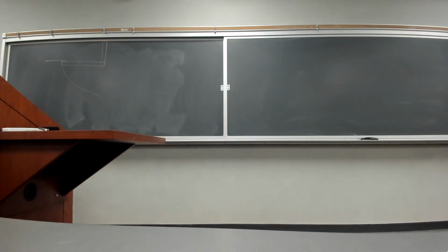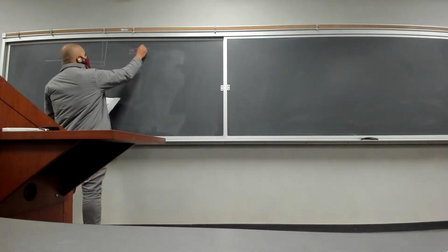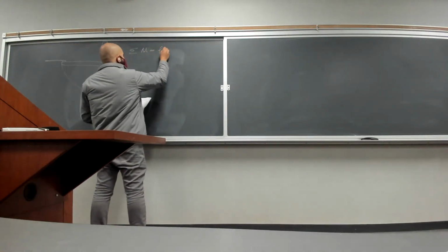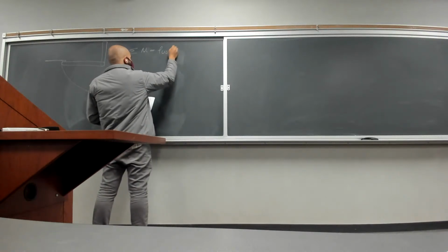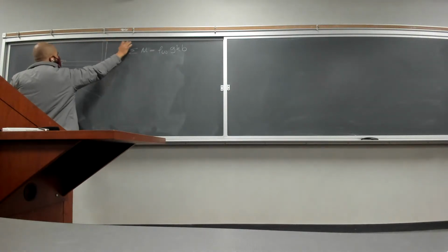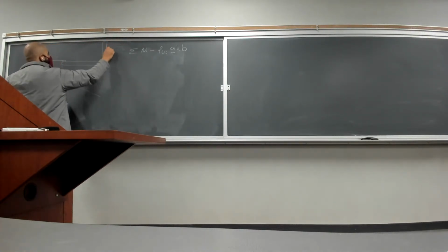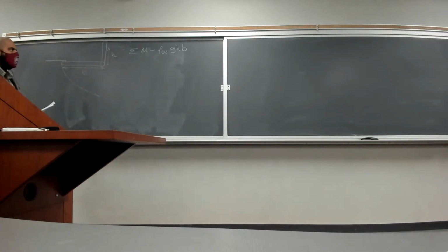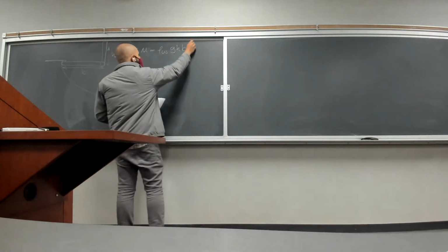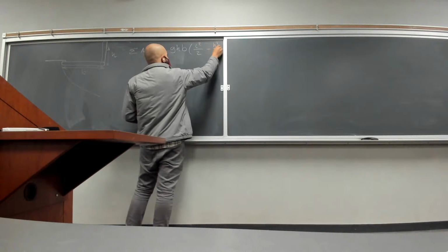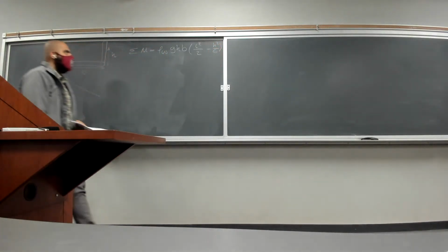Okay, and we wanted to show that the moment in the clockwise direction, which is going to be positive, is equal to density of water, gravitational acceleration, h multiplied by b, where this is h and this is b, times L squared over 2 minus h squared over 6.